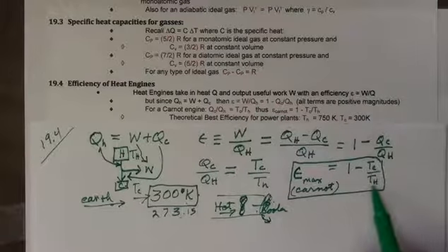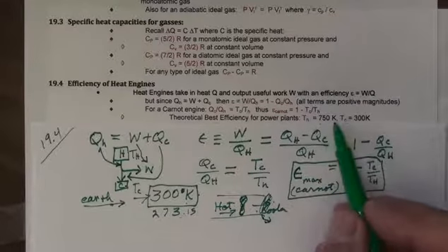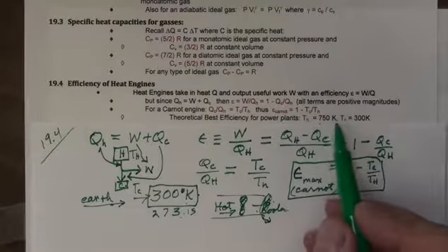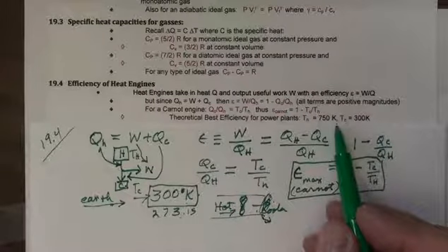But can't we get this hot temperature to be much hotter? Well, our temperature of 750 is about the best we can do, because above that we get much more expensive engineering problems. We begin to melt the steel. We begin to have valves and everything that don't operate properly. And so this becomes an extremely high temperature. And this is effective for both coal and for nuclear power. It doesn't matter what you're burning. This is about as hot as you can make the boiler.